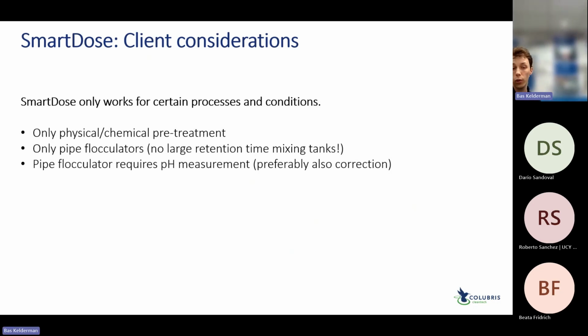There's no way for us to control the pH there. So what I want to do at that point is, well, I know this is just about 30 minutes, so I set certain limits to the pH where if the pH increases above a certain point, I just take my hands off the controls and wait for it to stabilize again, and then continue with the coagulant dosage. There's not really any point for us to waste coagulant in the meantime.